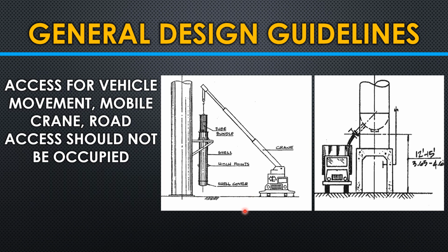So generally what happens in a piping layout development, due to various interferences and lots of coordination, there are times that engineers tend to make mistakes. The mistakes are such that they will go and occupy the access roads. So they will later come to know during the review that the entire piping has been made in the access road without knowing the importance of the access road.